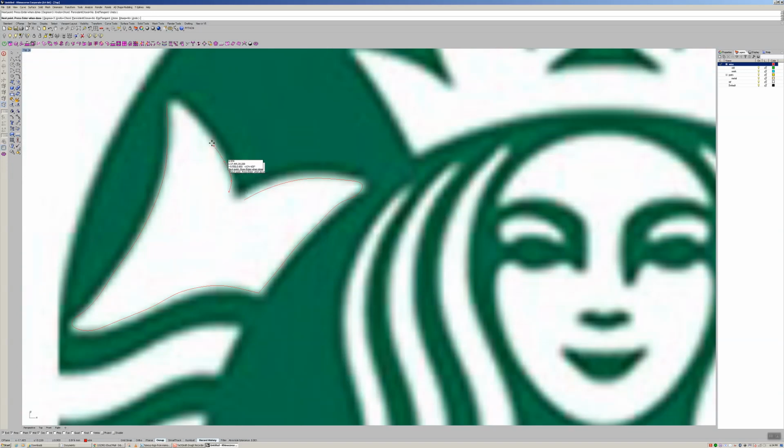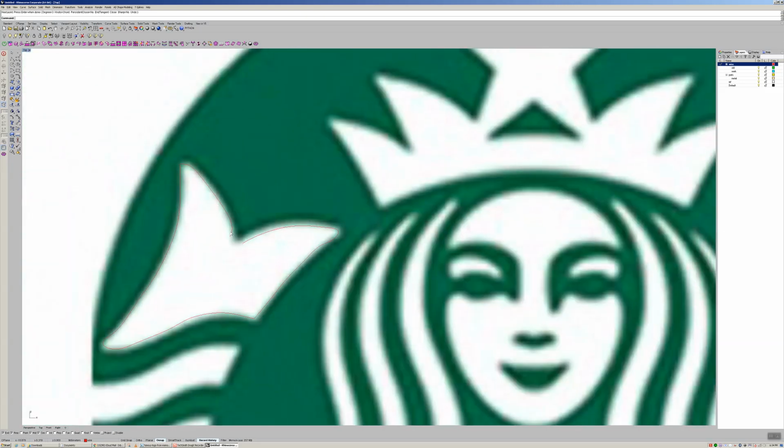Okay, one more time, right click to start. Now you see I must snap and left click. If you leave a gap, and I'm going to show you what I mean, if I leave a gap and I start here, when you zoom out sometimes it's hard to see that you missed a spot. But if this spot is open, that's going to be an open extrusion and you're going to have a hole. So we must fill that hole.